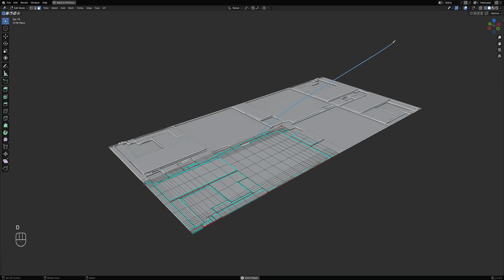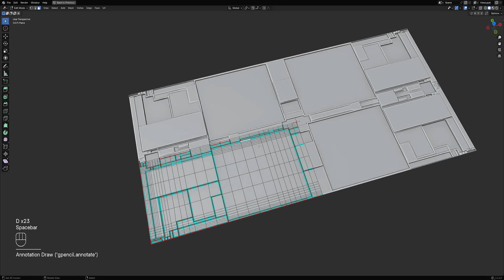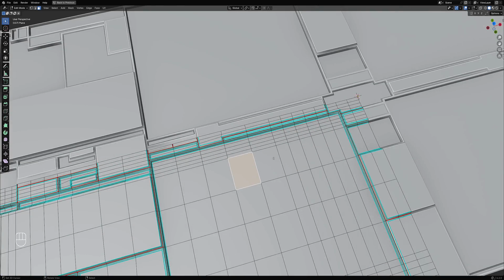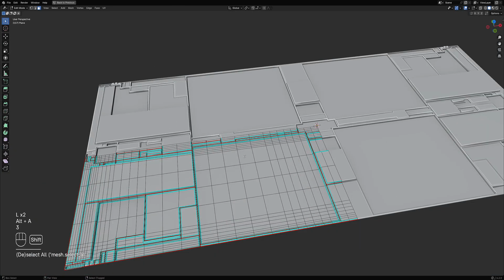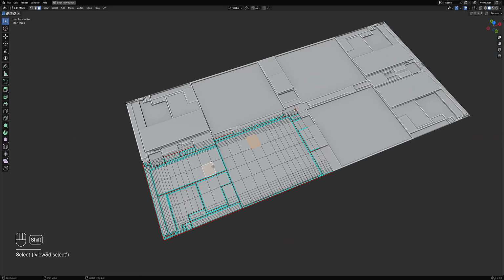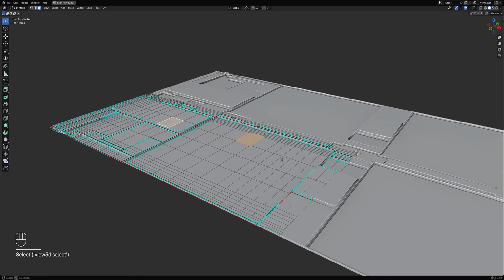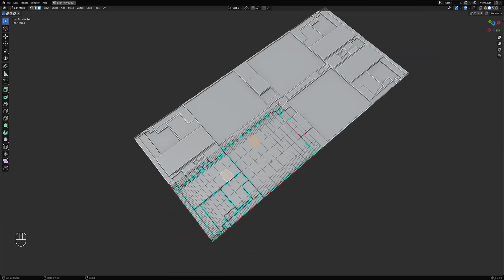That is where setting the offset property to off is useful for getting rid of the spiking geometry. But to avoid that, we'll use the Alt key event to select the faces that are connected to these flat faces, so thereby not including these ones here.